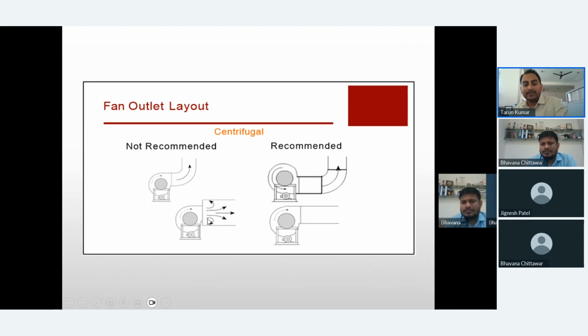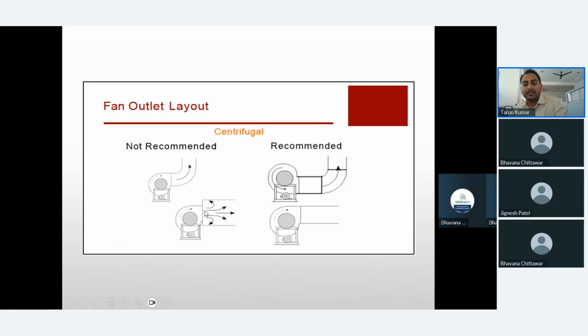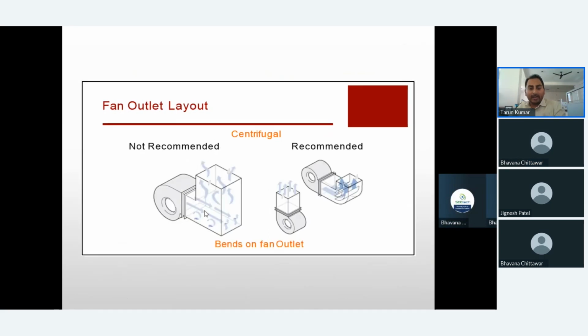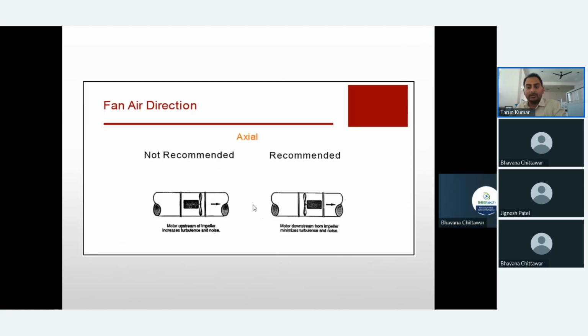At the same time, when you are putting in the duct, try to avoid oversized ducting. Try to put in the same size of ducting, because otherwise you can see air turbulence, and some of the air goes back, which again creates back pressure in the system. Further to that, with such an arrangement, rather than going for a 90-degree fan, you can directly go with the top discharge fan, and at least 2 bends are avoided immediately. So the right orientation of the fan is very important while making the installation.